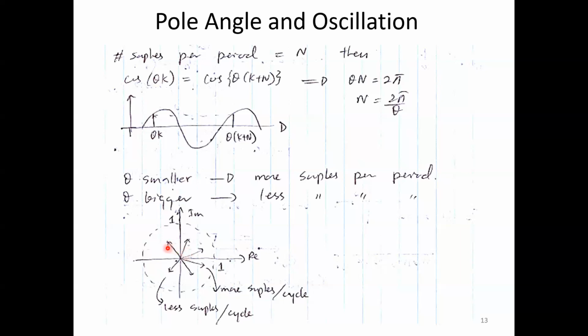Now, if you have poles over here, for example, negative half plane, your sampling angle is too big. Sampling angle is too big. So when we say sampling, sometimes we refer to the sampling interval or sampling angle. Sampling interval is in the time domain. You know the time in between two consecutive samples, right? But that is not really meaningful because you don't know how much the signal is changing during that interval. So therefore, much more meaningful information is the sampling angle.